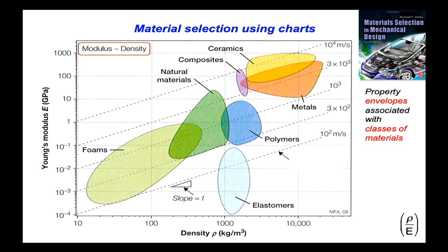Instead of just having Young's modulus and materials, let's, for the sake of it, as Mr. Ashby asked a few decades ago, put another material property along the x-axis. And as a result, I sometimes say bubble in my own head, but they're really envelopes. Envelopes that give us the bound of the family of elastomers that are available.